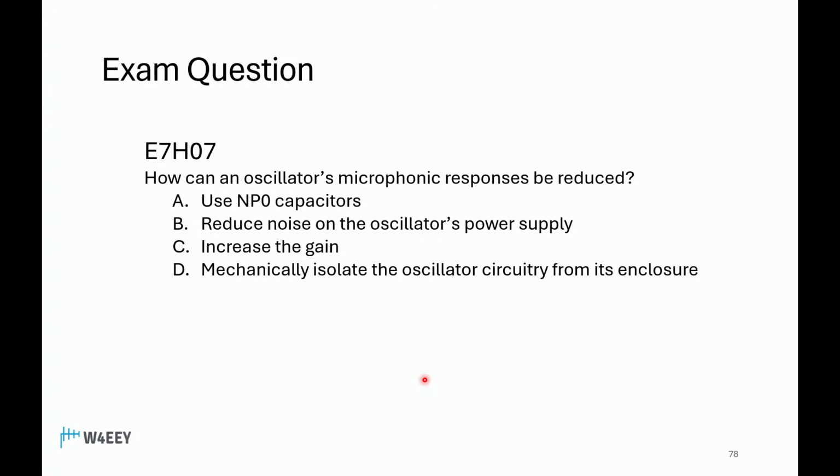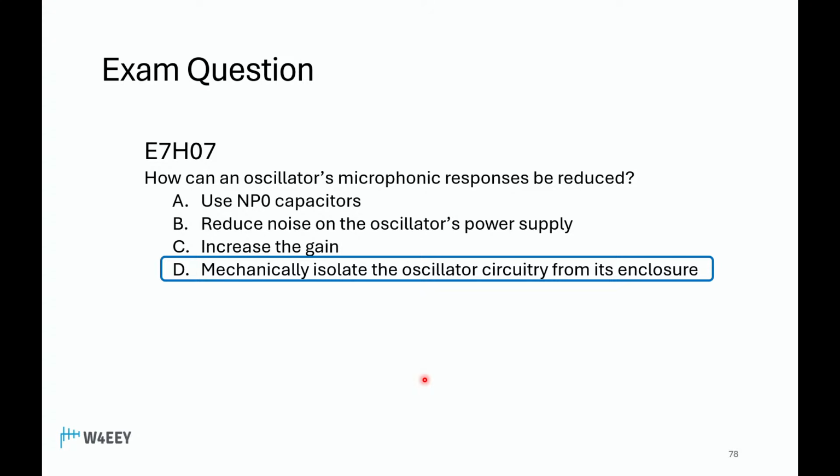How can an oscillator's microphonic response be reduced? Be careful on this one. Something that's very tempting. Alpha. Okay, microphonic response. Delta, yes, mechanically isolate. Yep. Now, the temperature drift, that's where alpha would come in. But they're asking microphonics, that's mechanical.